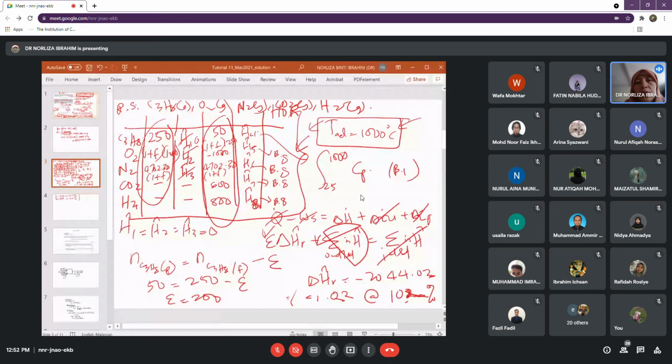So you give the different values of the enthalpy, and for the third assumption you give the table and then give the enthalpy. No need to repeat the energy balance equation, only for the first one. But the table too, I will always advise all of you to repeat the table, with the respective adiabatic temperature.